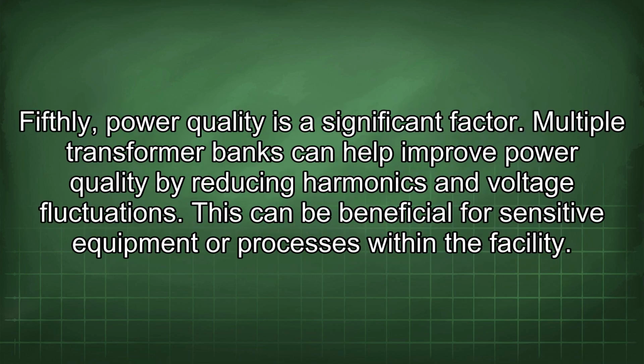Fifthly, power quality is a significant factor. Multiple transformer banks can help improve power quality by reducing harmonics and voltage fluctuations. This can be beneficial for sensitive equipment or processes within the facility.